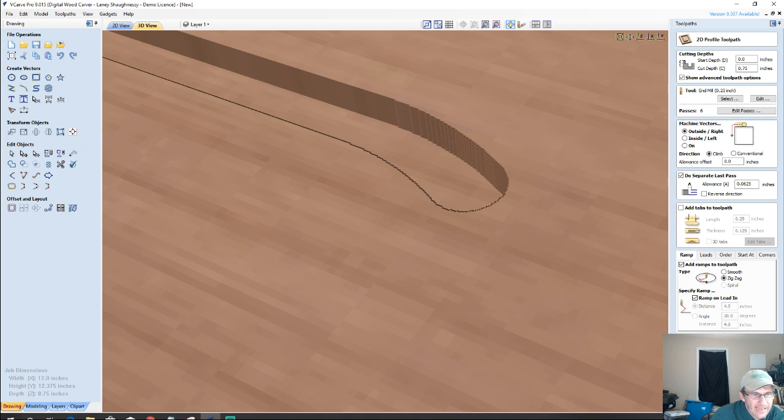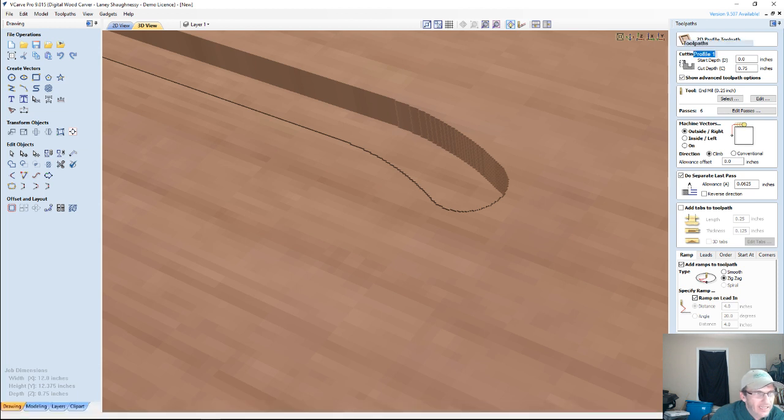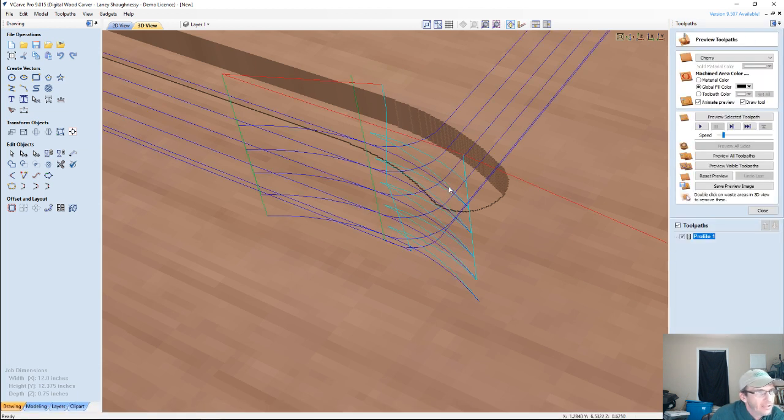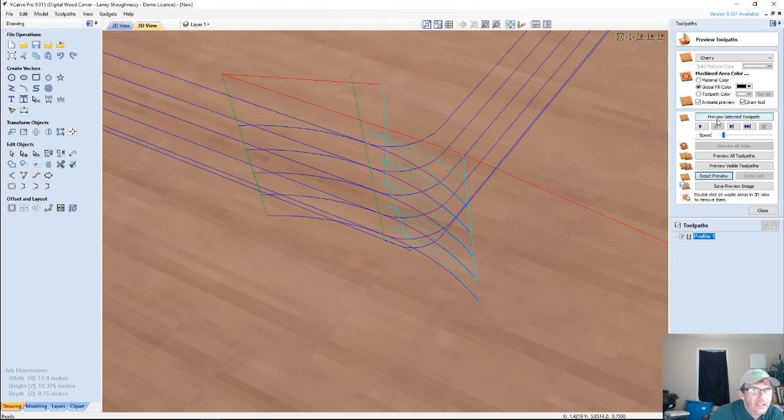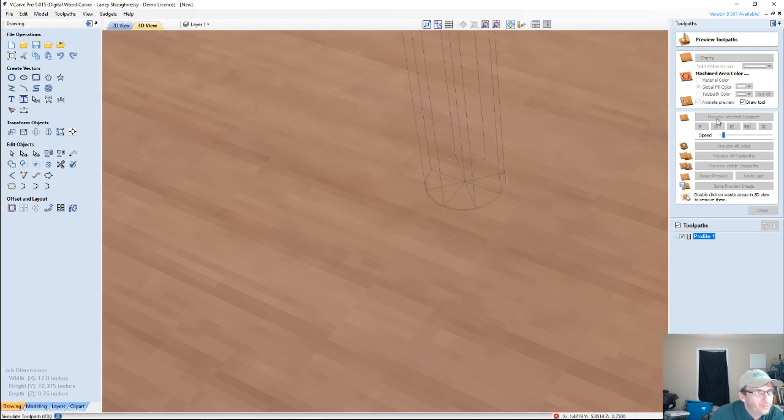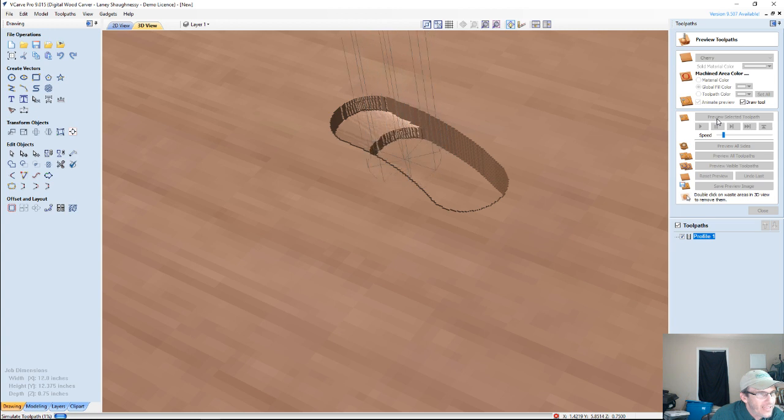On the zigzag, if I were to calculate that, you can see my lines here, this zigzag motion in the toolpath lines. If we reset this, it's going to start at a particular depth, come down, come back to another depth, and then come down to the final 1/8 depth. It's zigzagging down to that 1/8 of an inch cut and then it's taking its lead in.